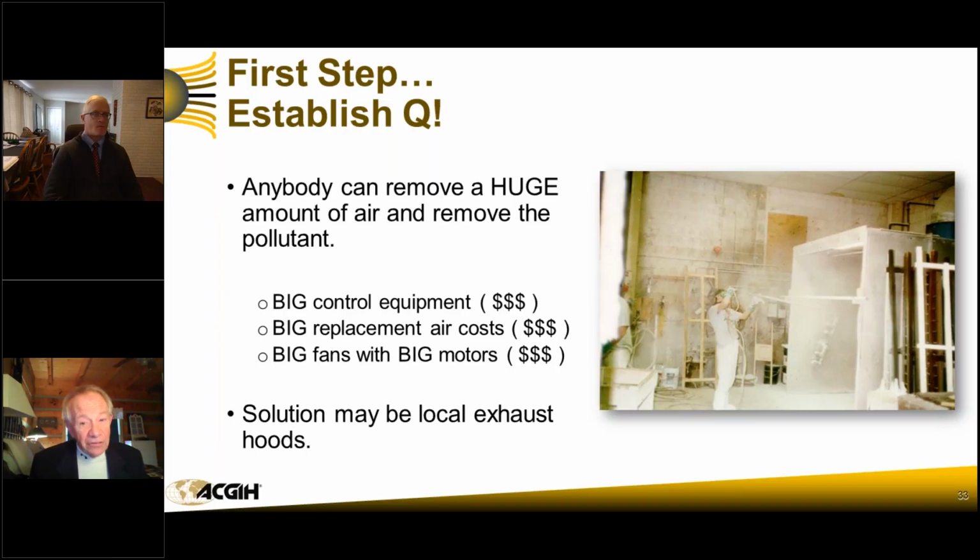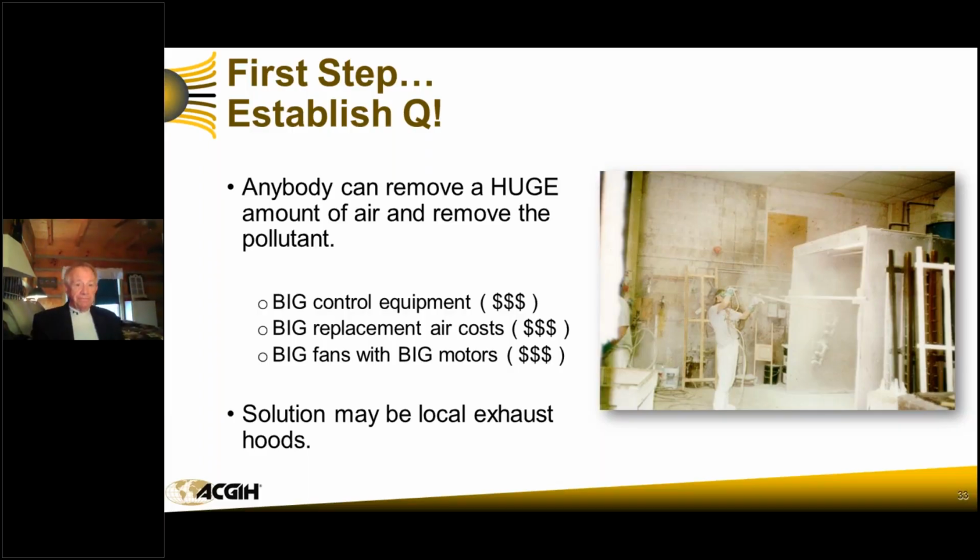Do you want to catch them as they come out of the opening, or do you want to wait and let them go out and graze a while and then have to go get them? It's the same kind of concept. If you can capture the contaminant as it's being generated, close to the point of generation, it's very easy to do it with a very small amount of local exhaust.